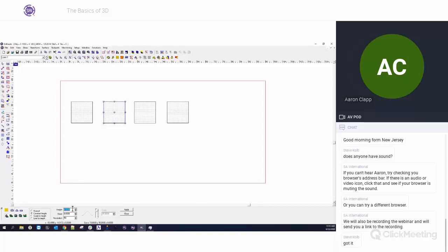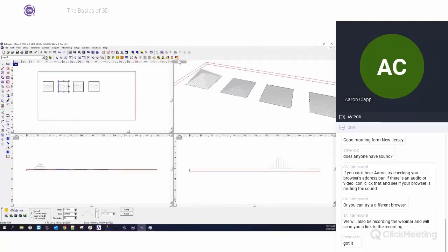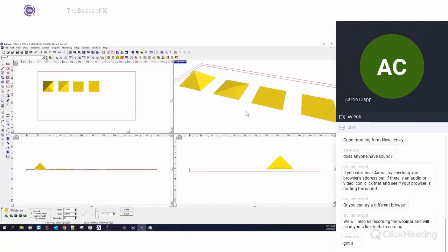So what we can do is we can say, I want this to be a maximum height of 0.75 inches. It will automatically adjust the angle for me based on the size of my shape and then create my object. So hit apply. And actually, why don't we go ahead and jump into the view so we can see what's happening here live. Actually, that might be helpful.